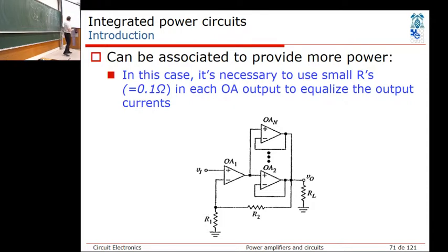But if you put a lot of those as voltage followers and short the inputs and outputs, which may actually end up with funny situations if you have big biasing voltages or currents on those amplifiers, this works in most operational amplifiers. So if you need a few times more than a single amplifier can supply, you put those as followers, and then you can drive it like that.